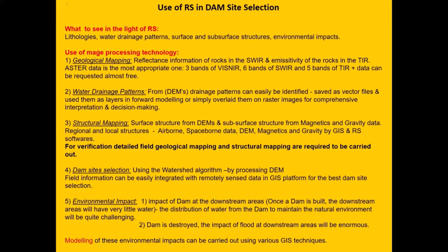So if all these are there, then there is a possibility, especially if it is present in the reservoir area, it's very dangerous, that it basically opens gates for leakage or seepage all throughout the life of the dam, and the reservoir with time will have a substantial amount of seepage, so that water storage becomes a problem.